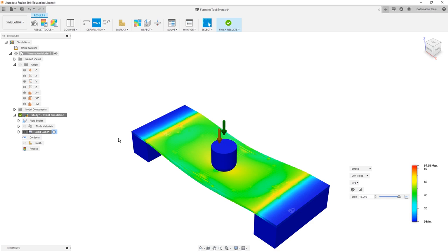Make sure that if you're not looking for self-intersections, or if you can solve any of the bodies as rigid bodies and omit them from the simulation, this will really help speed up the calculation time. And often if you notice that a simulation is hung for a while, go ahead and cancel the simulation solve, make some adjustments, maybe change some parameters, and then resolve the study.